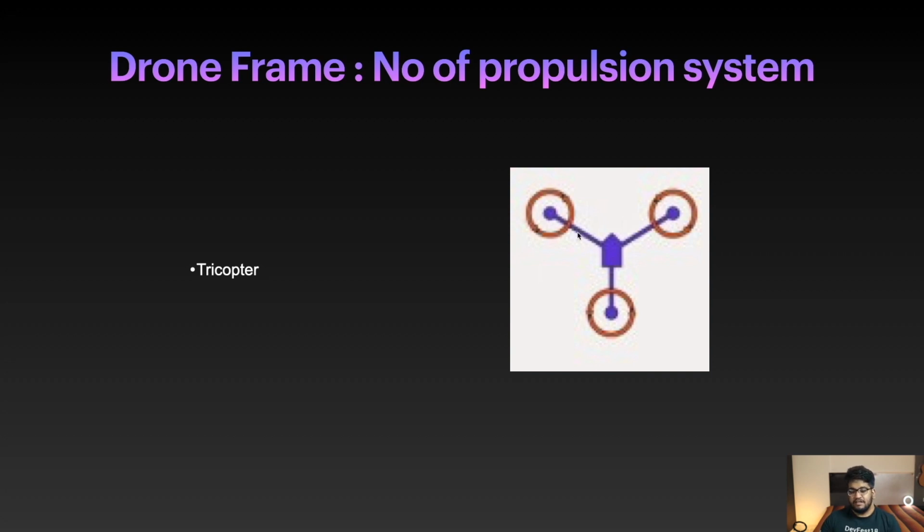And even in the last class, I showed you one video of a drone ambulance made by some university in the Netherlands. They are also using a version of tricopter. It's basically Y6, which we will also come to, but they are using a version of tricopter for the very same reason. They use this space to mount a screen and a camera to talk to someone who is assisting the patient. That is why tricopters are very much used in applications where you need this big clearance, and you will not find this clearance in a quadcopter, as we'll see in the next slide.